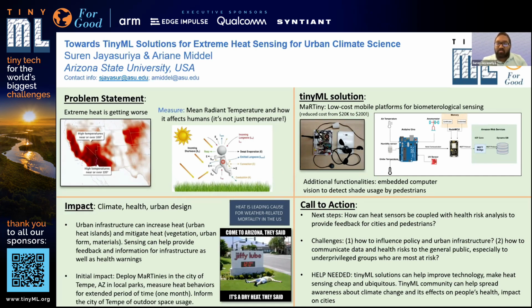So we're just proposing a small solution to get more information, which is we are building these devices called martinis to measure MRT, or mean radiant temperature. These are low-cost mobile platforms for biometeorological sensing. We've reduced the existing setups, which actually are $20,000 with really expensive sensors, down to a $200 prototype that uses an Arduino Uno and a NodeMCU microcontroller connected to a bunch of different sensors like wind sensor, air temperature, humidity, UV. And that data is being collected and computed, and we are performing machine learning models to determine mean radiant temperature.